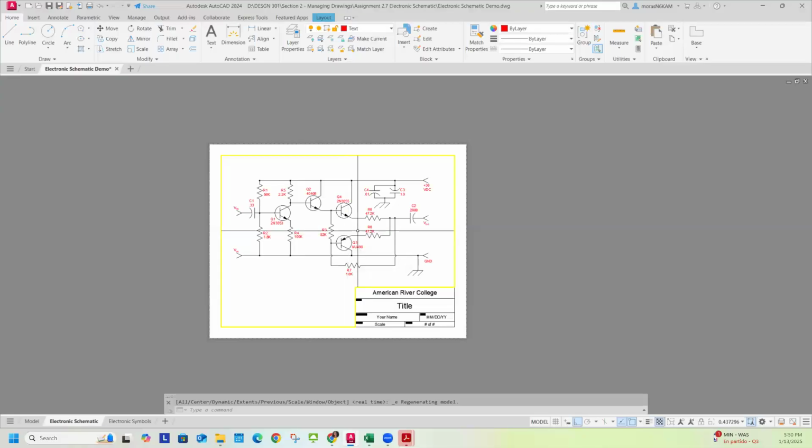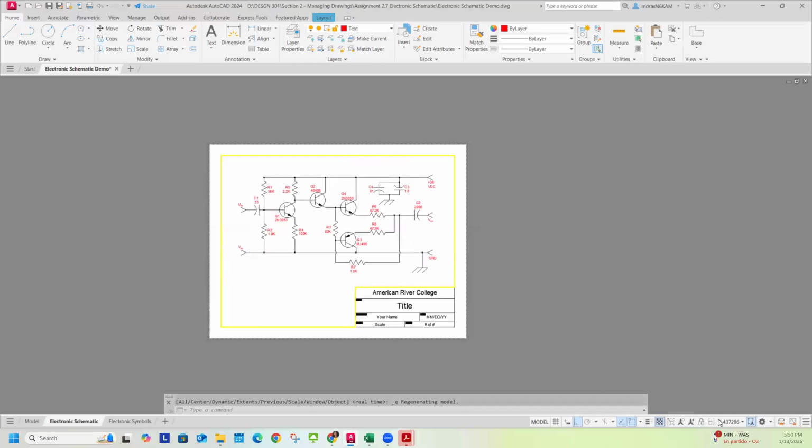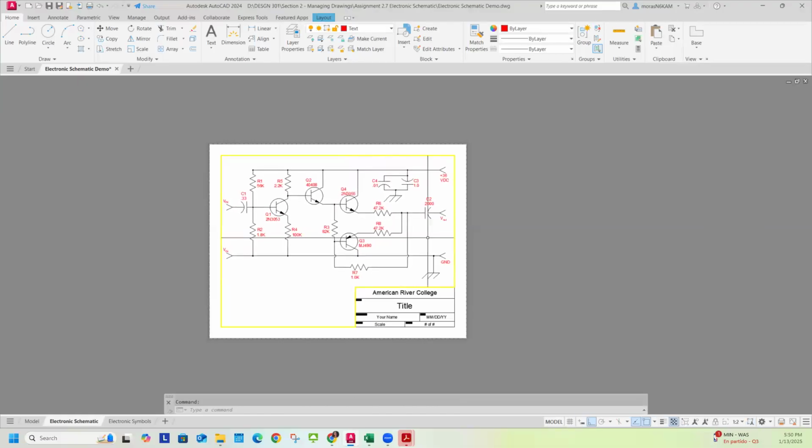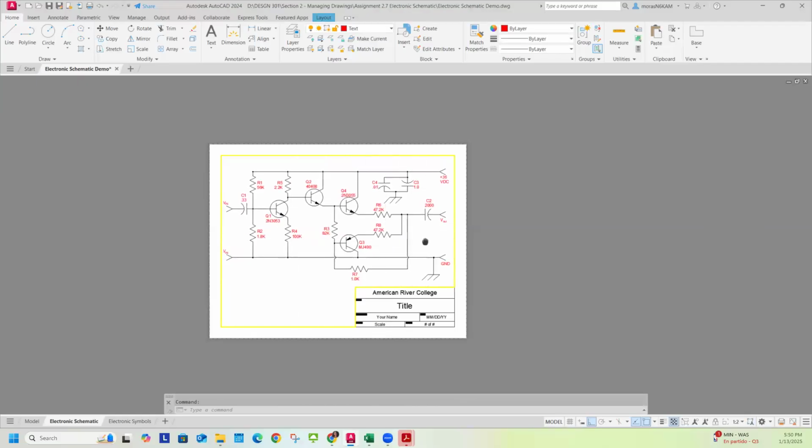And if you notice on the assignment it says NTS for the scale, that means not to scale. So you don't have to make it a nice round number like we normally do. I do like to have it be a nice round number, and so I could just go like that, but it doesn't need to be because we aren't stating what the scale is. Okay, so I will go ahead and lock that.